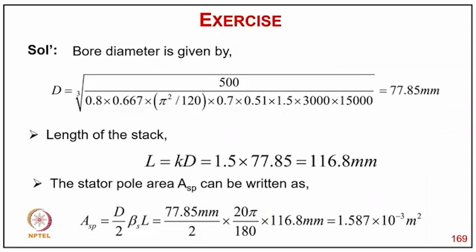So from the formula, the cube root of the dimension power, D comes to 77.85 millimeter. Length of stack L equal to KD, putting in the value, 116.8 millimeter.